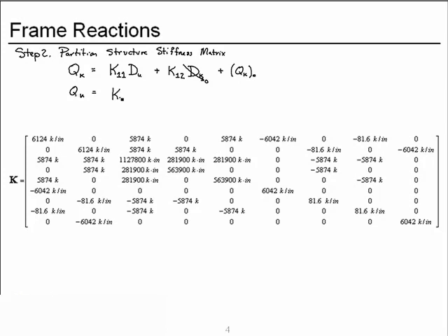And so we use this piece of the stiffness matrix. Forces at constrained degrees of freedom due to deformations at unconstrained degrees of freedom, so we need to multiply it by the unconstrained degree of freedom deformations that we will have just calculated using that equation. And this portion of the matrix if we have support settlements, but we won't need this portion because those deformations at the constrained degrees of freedom are 0.